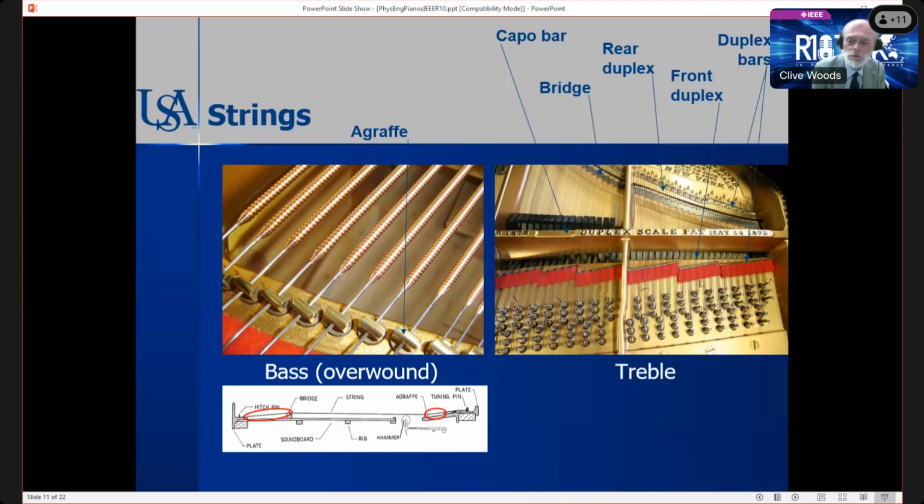So by using a duplex design, much less energy is taken away into damping felt, and then you probably try to tune those strings so that if they vibrate they're not objectionable. So I think really that's what's going on, and all high quality pianos have duplex bars front and rear. Steinway, I think, probably originated it. Yamaha and Kawai, Mason and Hamlin, Fazioli, Bechstein all use tuned duplexes.